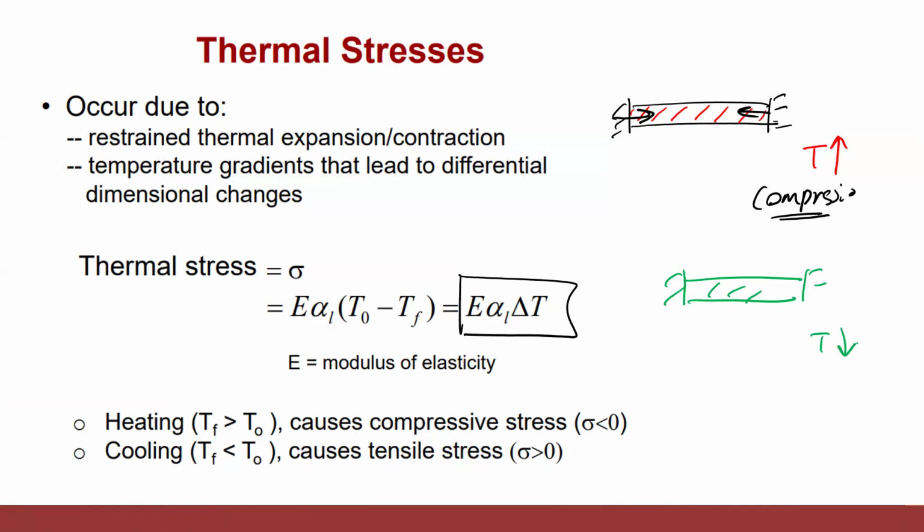Similarly, if you decrease the temperature, what will happen? When you decrease the temperature, the material is trying to shrink, but the supports are pulling it. So what kind of stress will it undergo? It will undergo a tensile stress. Am I right?